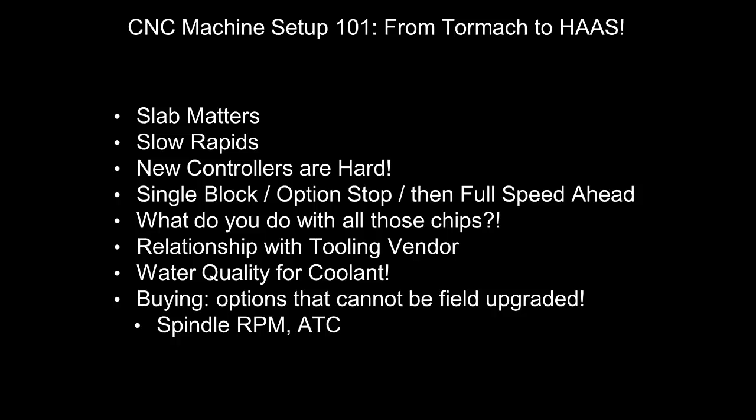Stuff like that. One thing I don't like on the Haas controller, which will never change, is you have to put a decimal point after every value. So to enter 1 inch, it's not one enter, it's 1 dot. And Tormach never had to do that. So that's kind of a weird thing where I have goofed once, I will admit, because I added 1, which I think ends up being 1/10,000,000th or 10 millionths instead of 1 inch. And that's operator error that will cause you to crash a machine.